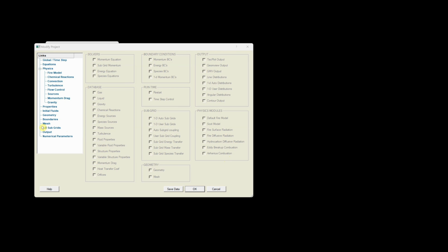Okay, now the next step is to create a mesh. So I'll click on mesh, and we have to do it in all three directions, X, Y, and Z. This was the default that it came in with, but the best way to do it is to allow the code to scan the geometry and find points that are relevant that you want to map to.